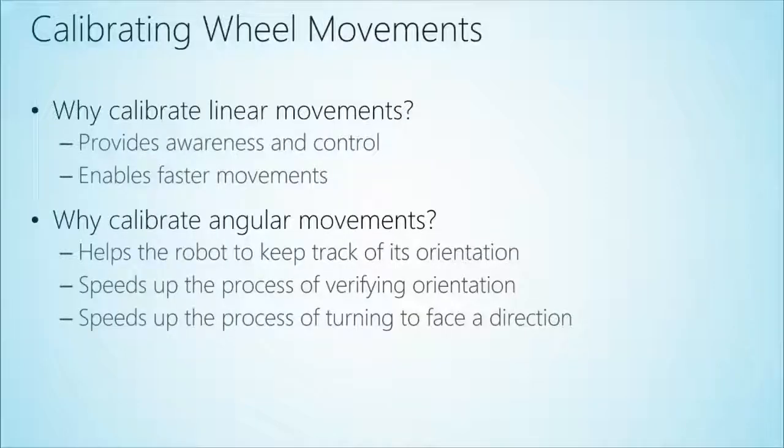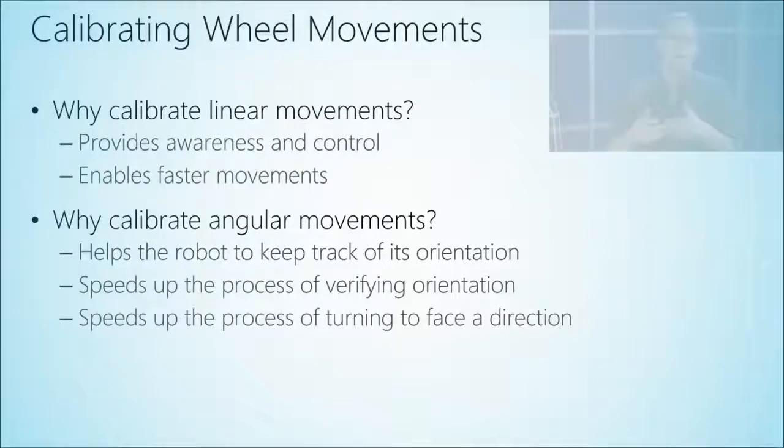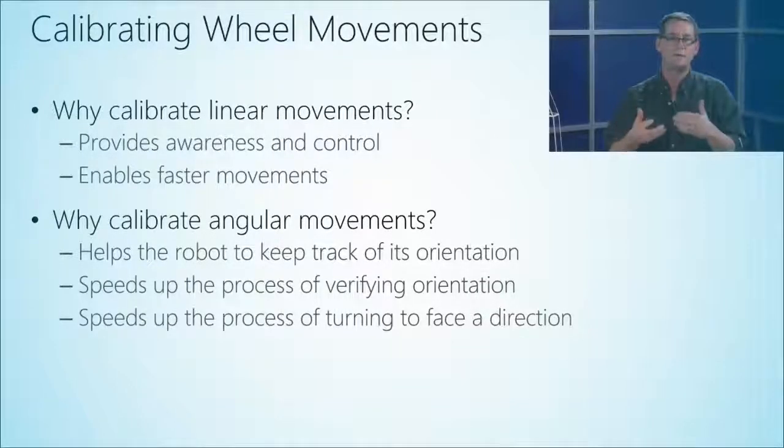And so now we're going to talk a little bit about wheel calibration. One of the things we have to recognize is that taking these sensor readings, because we need to filter, takes time. It takes almost a second to take 50 readings spaced at 40 milliseconds, maybe 2 seconds. Boy, how's my math? So it's taking some time.